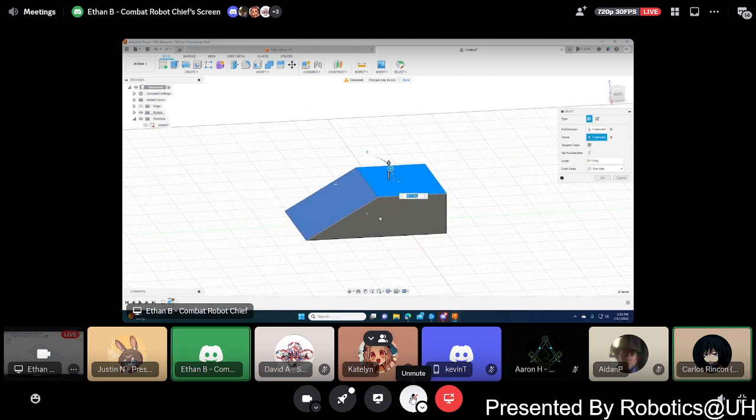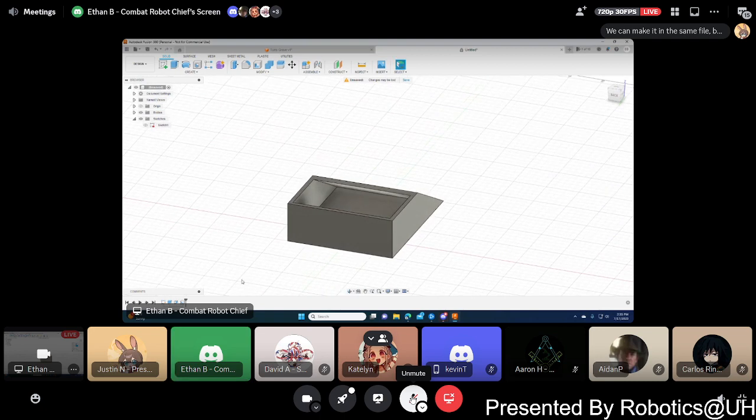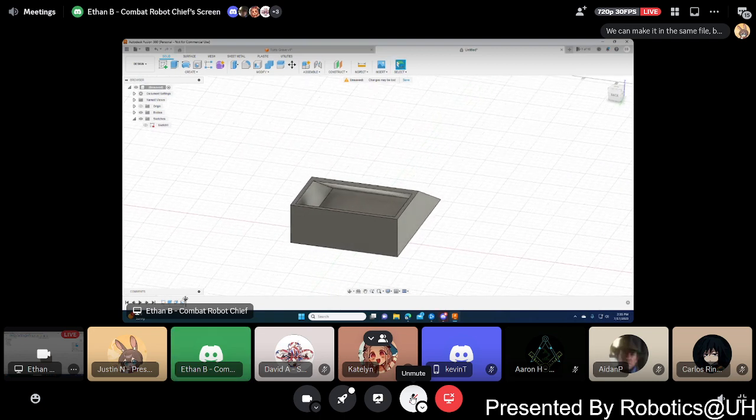So I made the draft using that. I'll click enter, and let's see if it did what I think it will do, and progress the timeline forward to where the shell was. Yes, it did. So with this tool, you can change the order of the features in the timeline, which changes the order in which things happened.